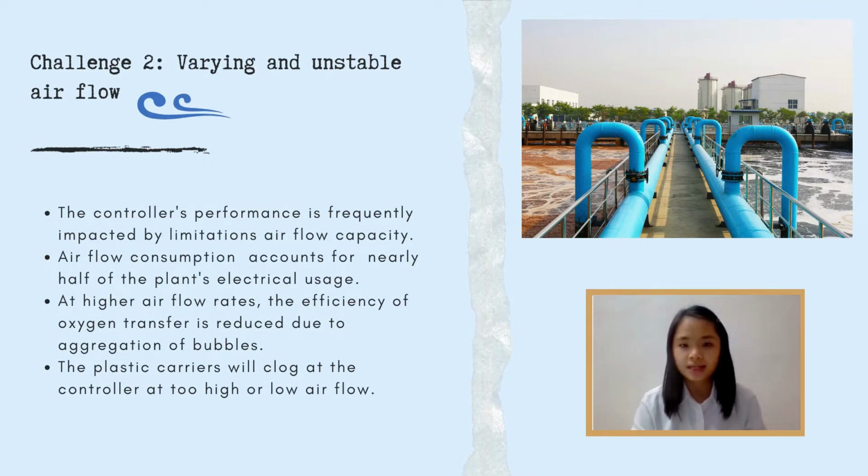The second challenge is in full-scale plants. Assessing the energy saving potential using airflow measurements is challenging. Airflow consumption is critical because it accounts for nearly half of the plant's electrical usage. The controller performance is frequently impacted by limitations in maximum and minimum airflow capacity.